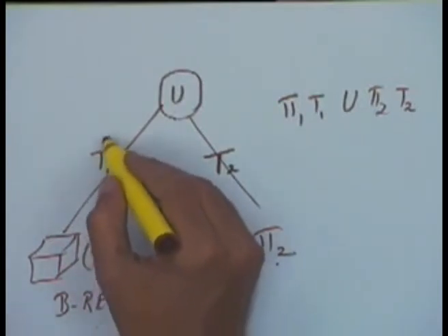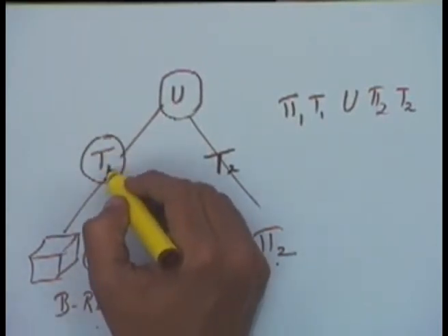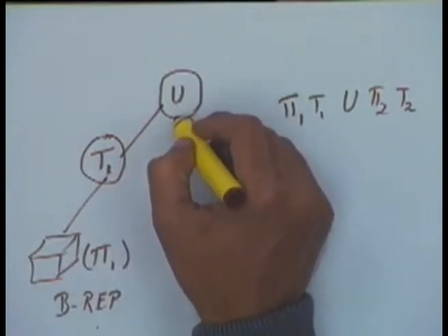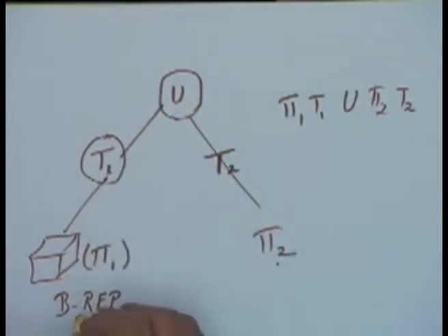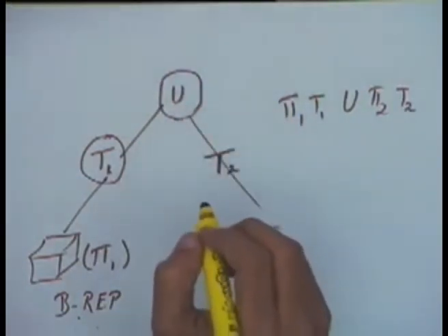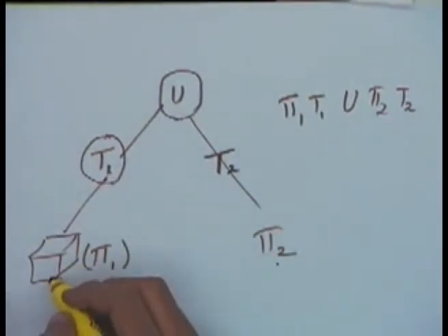Okay, so these transformations are normally relatively simple to use. It's only the Boolean operations which are expensive in terms of evaluation. If you are talking about a transformation that does not change the topology of the object, only the Boolean operation would do that. Transformations would change the properties of this solid.